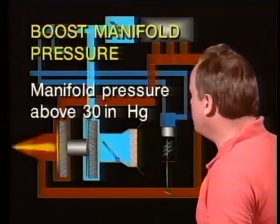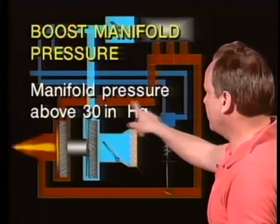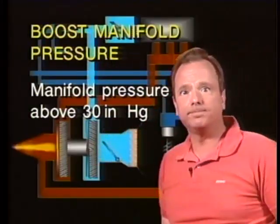Now, if ambient manifold pressure, ambient air, is 29, 30 inches, so if you have manifold pressure higher than 30 inches, that is a magic word. That is called boost manifold pressure. It's manifold pressure above 30 inches of mercury.